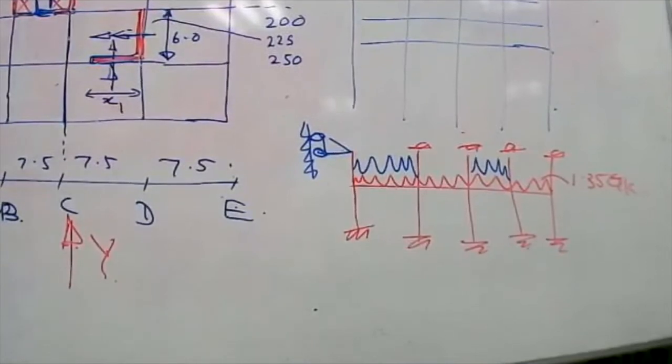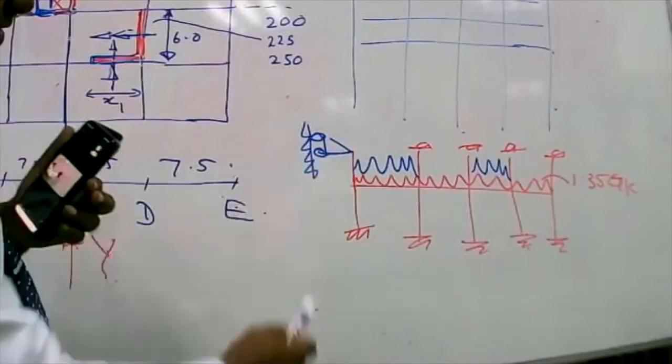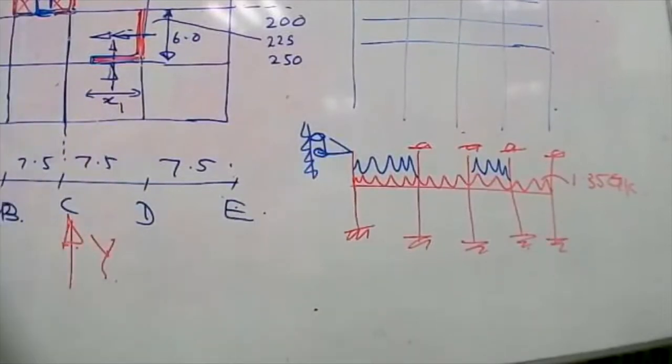Don't assign a fixed joint. Assigning a fixed joint means the column is fixed, hanging from the sky, which is wrong. Always allocate a moving joint in the vertical direction at the top of the column.